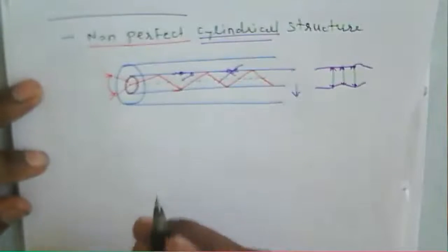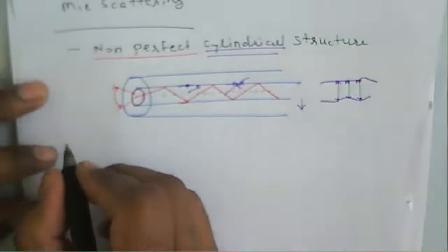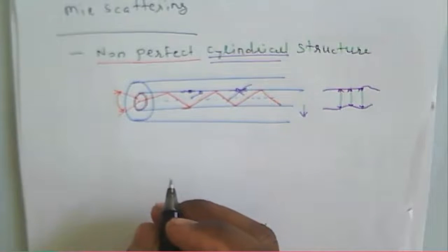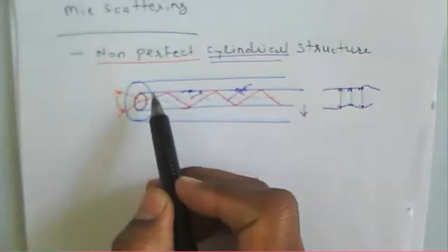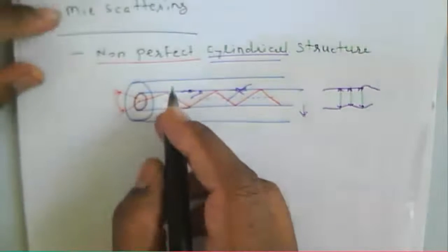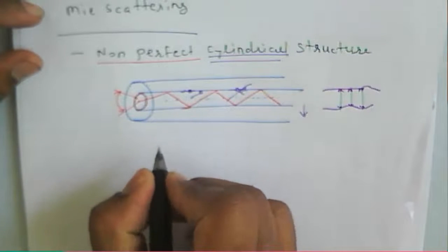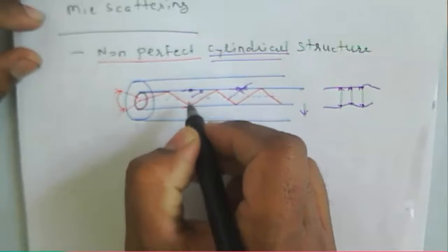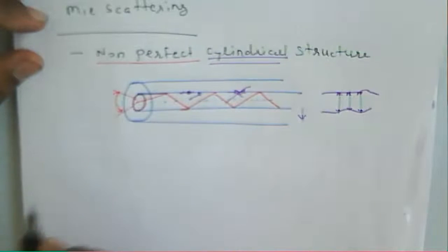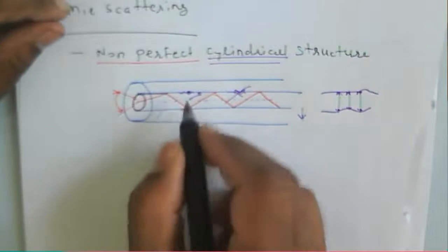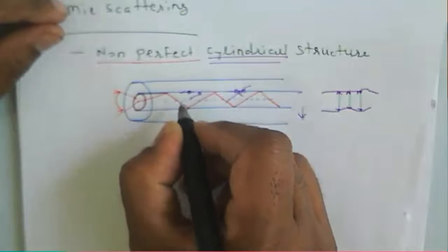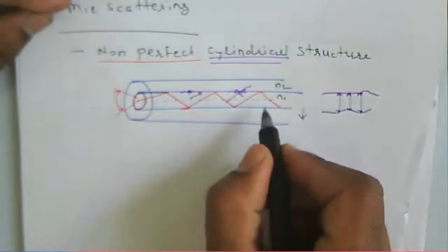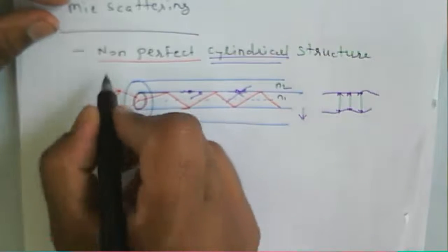Now, how do we reduce the Mie scattering loss? To reduce it, we need to remove the imperfections due to the glass manufacturing process, at the time of manufacturing the fiber. We also need to carefully consider the boundaries made by the fiber, or the coating used on the fiber. Or we can increase the fiber guidance by increasing the relative refractive index difference: if we increase the difference between n1 and n2, the guidance mechanism will be increased. So these are the ways to reduce Mie scattering.